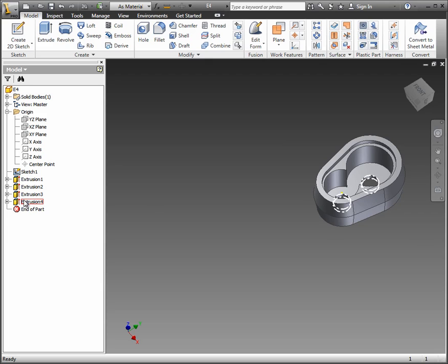It wasn't updating. So what you might want to do is, if you accidentally forgot to put in the 4, or the minus 4, or you messed up the directions, my suggestion is, if you see the plane in the feature tree, just click on it and hit delete. And then let's just re-add it again.